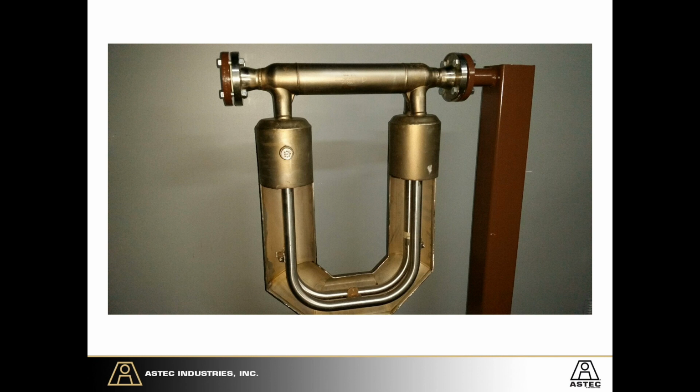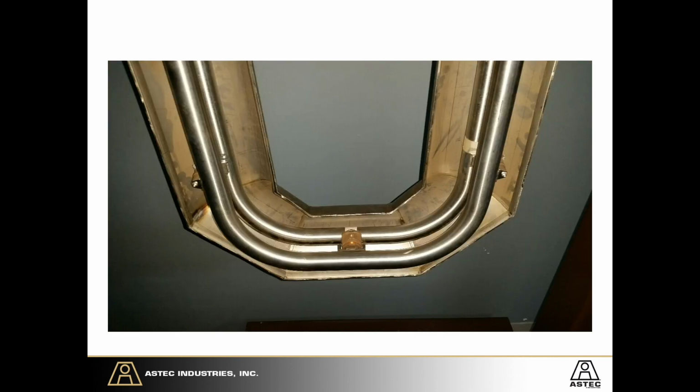Here's a kind of a breakaway of one that we have at our facility. You can tell it's pretty simple, not a secondary pump. The AC enters in, flows through this line here. You have these two pipes that are acting like tuning forks. And these tuning forks have sensors on them, and they can actually sense how much AC. They do a couple of different things too. They also look at temperature compensation, and here's a better view of this sensor that you can see here.